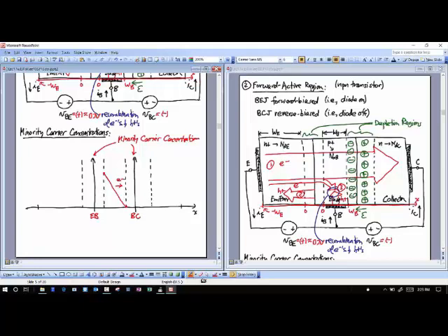And so I have to worry about all these currents, and that's the reason why I make the emitter N+, and I make the base P or P+. This would work better if the base were P, actually. I'm showing P+, but sometimes it is P+, because you're forced to do that in fab. But I want my emitter to be the most heavily doped, because if I make the emitter heavily doped, that makes this current number 2 smaller, much smaller than this current number 1. And I'll tell you why in just a second here.